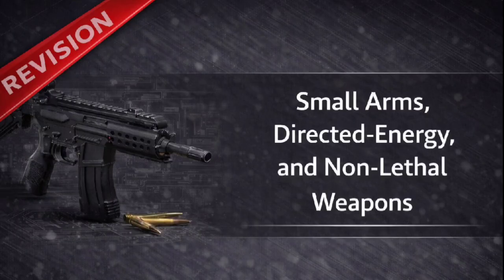Okay, so what about taking gas near the muzzle? Gas near the muzzle is cooler, but this drop in temperature causes the carbon to solidify, to desublimate. This leads to significant fouling and carbon buildup in the system. So there's a sweet spot. There is. The engineering compromise for optimal reliability is usually struck somewhere between 20 and 30 centimeters from the muzzle.